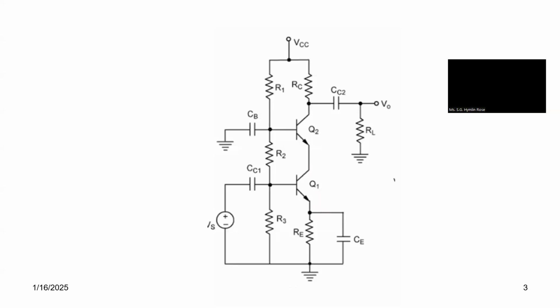The Miller effect is when a small input capacitance appears much larger at the input of an amplifier. Because of this, you achieve high input impedance from CE, and high output impedance from CB. These are the major advantages of cascading these two types, so good gain and bandwidth.